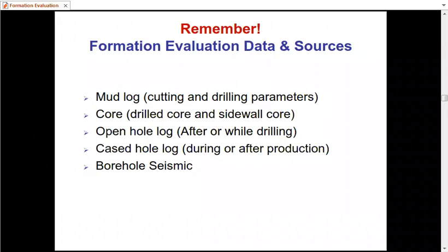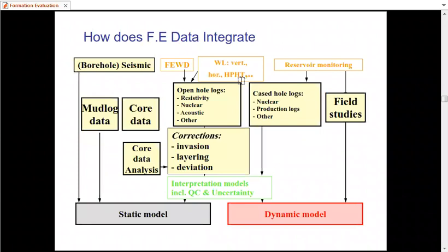Also the open hole logs after or while the drilling operation, and cased hole logging during or after production operation, or the production life cycle of the well. The last formation evaluation data source is the borehole seismic. Yesterday, we talked about the integration of the formation evaluation data, starting from the static model: borehole seismic, mud logging data, coring data, also the open hole logs data. And the second phase is the dynamic model, starting from the cased hole logging and the field performance or field studies.